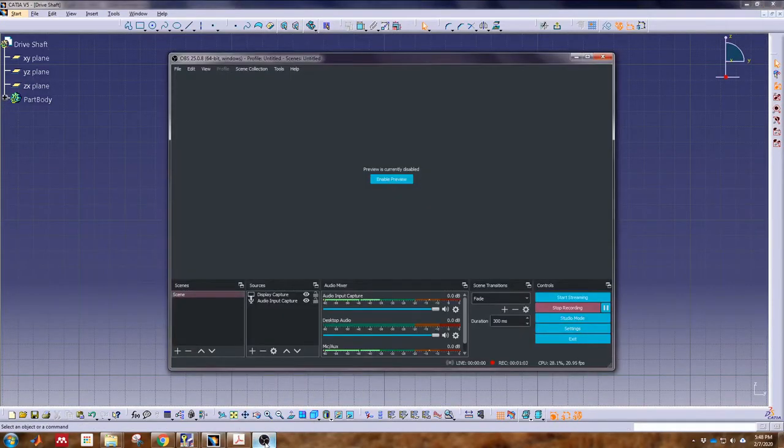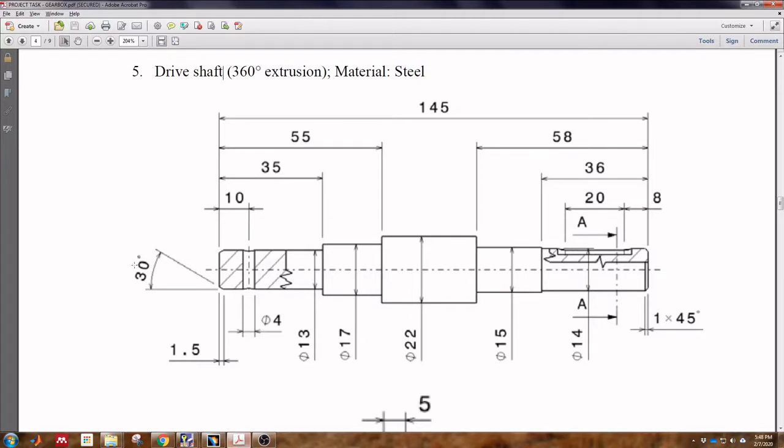So we go back to the drawing. We look at the drawing here. So we have the complete shaft like this. The strategy of creating a 3D model of this sketch is by first drawing the half part of the sketch only, and leaving all the parts that can be made during our 3D projection, for example the chamfer, the hole, and also the keyhole.